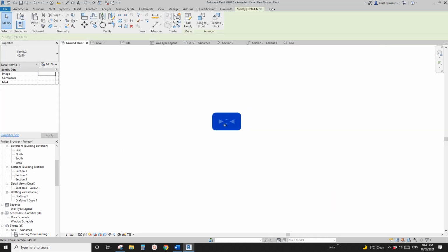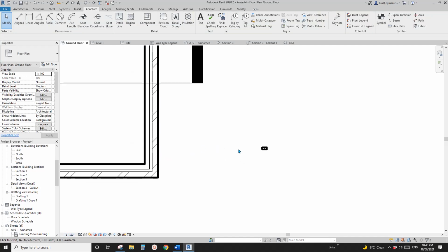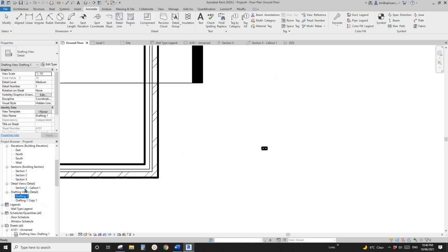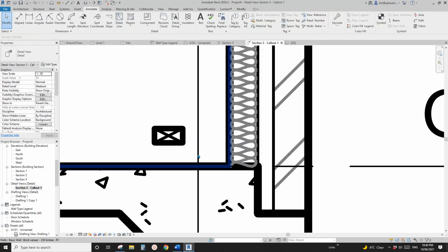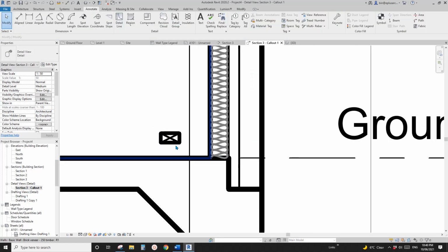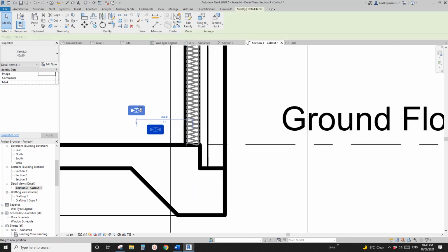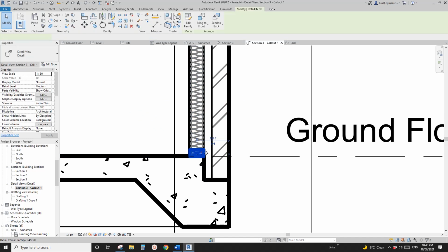Yeah, the line weight looks okay, I think, because this is floor plan. I'm going to copy this into my detail view. Okay, so detail, Control V, just check the line weight. I think it's okay compared to this. I think that's fine. So you can just manually place them. So for example, I'll place it here.